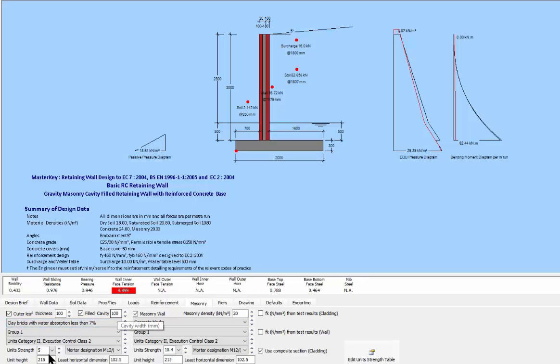and we have a filled cavity. Now again, let's look at our wall, and in this wall we're seeing that this is the most important. This is just the shuttering for the concrete. This is the compression zone. So we want to put in bricks or blocks that are going to work. So again, I'm going to stick with blocks, and I'm going to up this to at least, sorry, wrong direction, 10 Newton or 17 Newton. So we'll go for 10.4, a standard block.